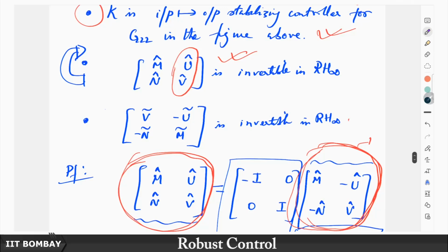If you want to prove the third part of this, once again you have to take the other side, the left co-prime factors. We have taken the right co-prime factorization, you have to take the left co-prime factorization. So, that also I leave to you as an exercise, exactly the same set of steps. You start with the left co-prime factorization of the plant and the controller, and you will arrive at a proof for the third result. So, we have shown the equivalence of 1 and 2.